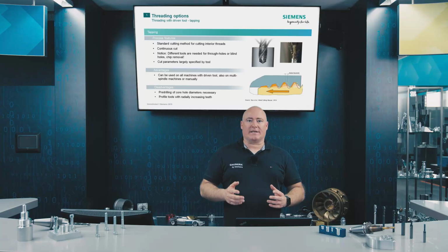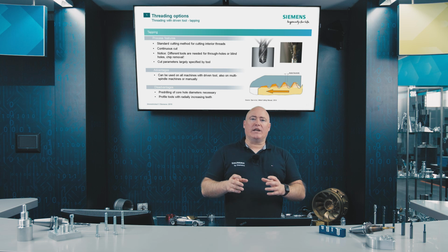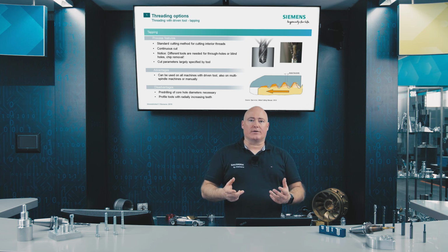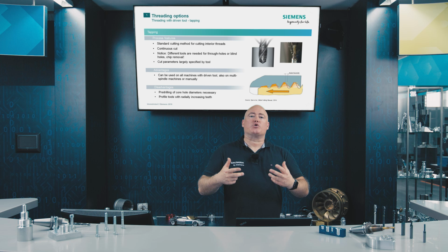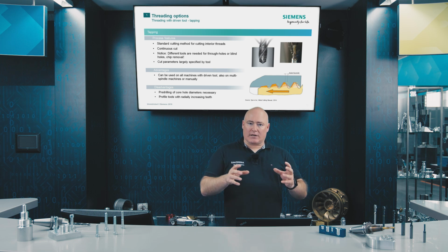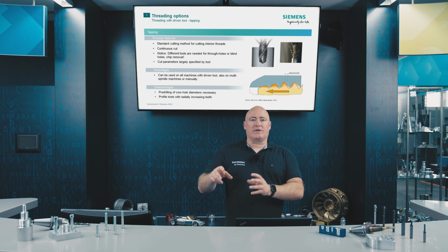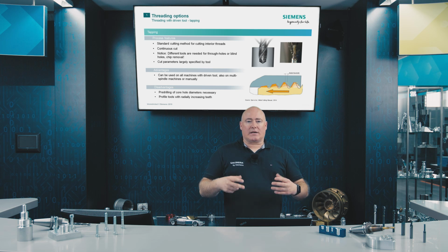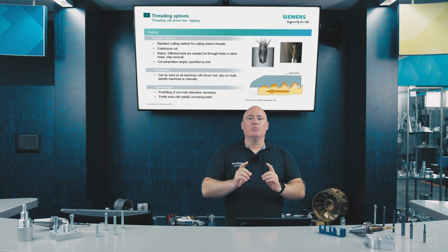The standard cutting process for female threading is tapping, also commonly referred to as thread cutting. The corresponding, in other words the correct, profile tools or the appropriate taps are required here for each thread size. We must consider two different types of drill holes here, the blind hole thread and the through hole thread. The blind hole thread stops at some point within the material and the chips must be conveyed upwards with the corresponding tap.